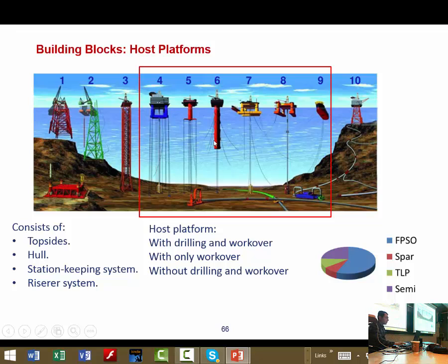payload. And the reason why you need a storage capacity here is, for example, when you have a pipeline system, you may have a failure in the pipeline system. For example, the pipeline system which you are connecting to is quite an old pipeline system, and there is a high risk of failure in this pipeline, and then you should estimate, for example, 1 week of shutdown or 1 week of stopping export. Then you should consider sufficient storage here, for example, a few days, just not more.